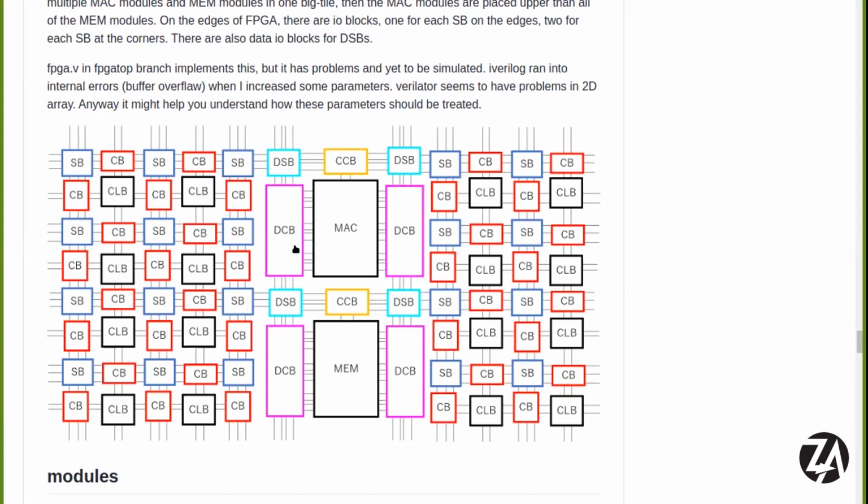Interestingly, our multiply accumulate unit, when we first built it, was too big. How many bits wide is the multiply? It was 32 bits by 32 bits, and then because it's an accumulate, the output size was doubled. Well, it's 4 times that, because you need double the width just to get a product, and then we have 4 times that for a successive accumulation of those products. And that was huge. That would have been about a quarter of the size of the Caravel die that we had, the user space we get. So we were like, okay, maybe that won't fit.